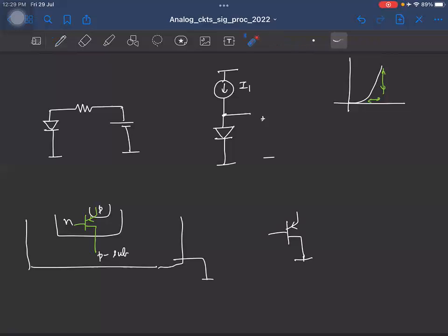So you have two diodes between emitter and base, and then one more diode between base and collector, right? And the collector is grounded. I just want one forward bias diode. So obviously I will short this to ground, so that the diode is inactive. Okay. So this is how we'll finally realize it on your chip.